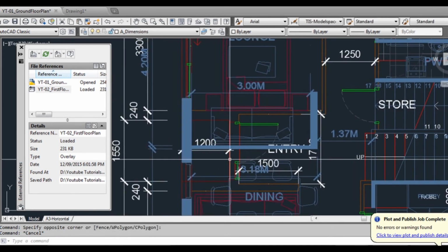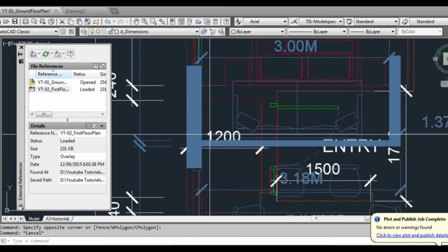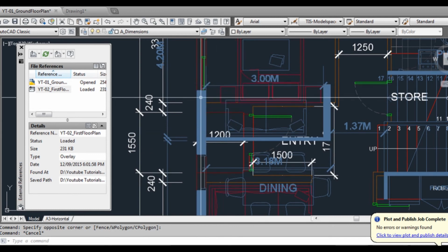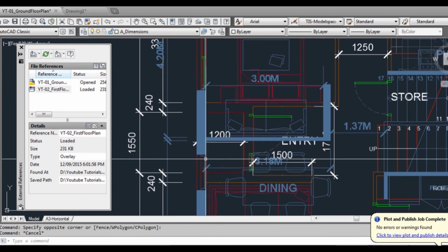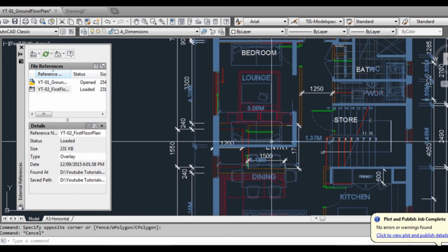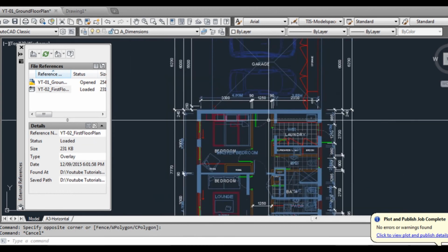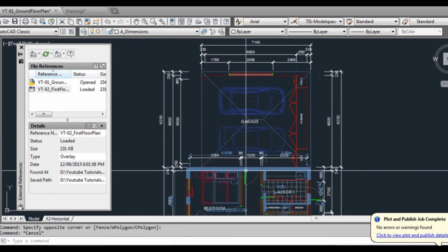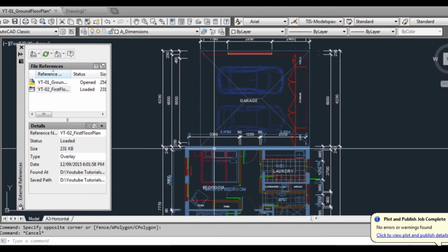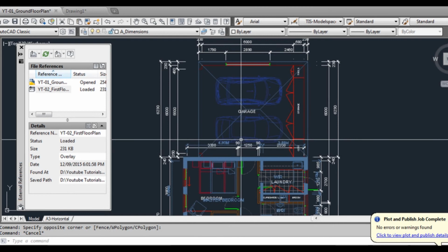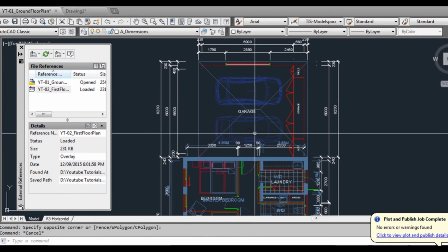As you can see here, with the first floor plan over, we can see that this bit that juts in here is on the ground floor plan, and over here there would need to be a beam or something, because that's a wall that's going straight over that opening, and there's another wall that's going over there. So it helps to really look at the structure too. Structurally you can sort of see how things are going to be. You can see how lines and load-bearing walls are, and it's quite good in that way. We will use this in the next chapter as well, when we set up our elevations and sections, and I'll show you a couple of techniques for that when we get to that.